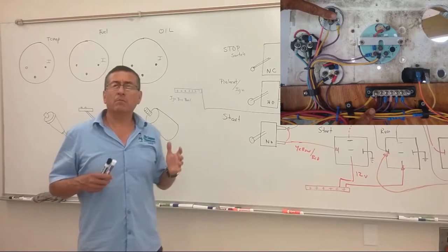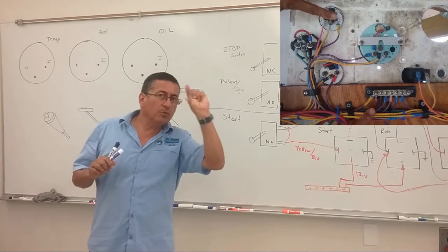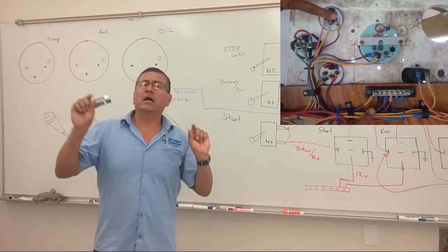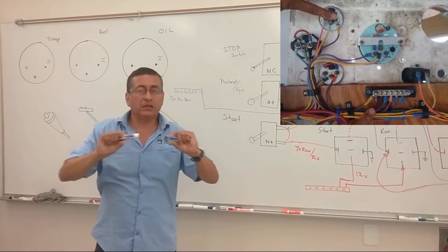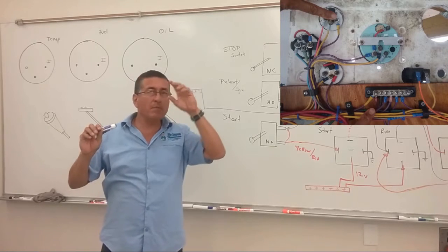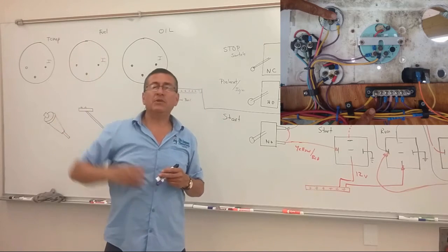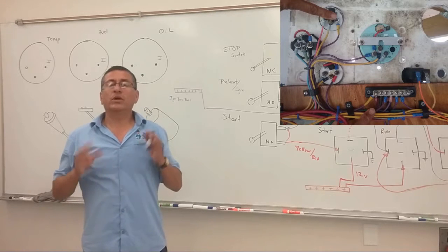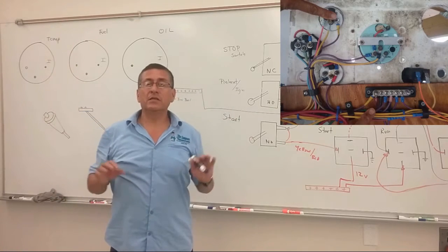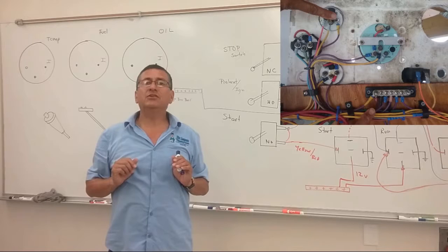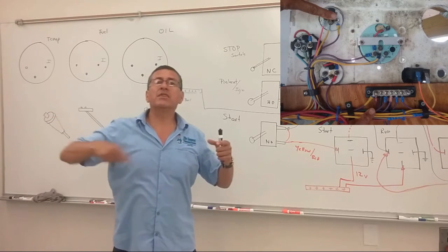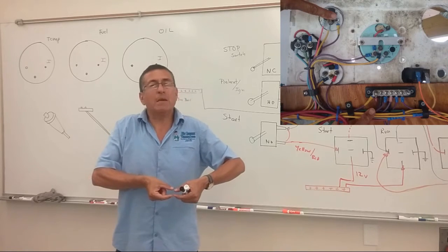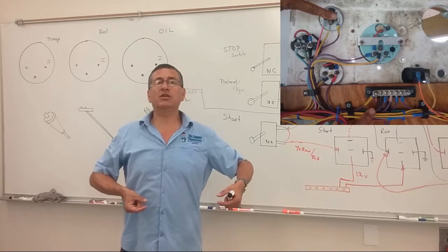Normally, when I wire both, I create a smaller ignition bus bar, and I create a positive bus bar, and I create the negative bus bar. Very important. Remember, in the previous episode in other chapters, when you have different groups of batteries, the most important part is to connect all the negatives of each group of batteries together, and together with the main negative bus bar in the engine room.